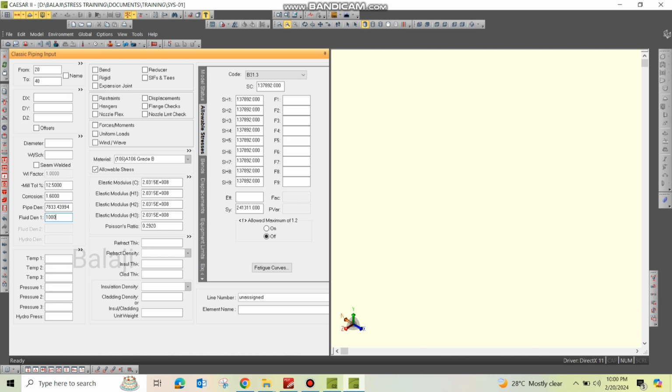In some projects, in the stress design basis as well, clients provide the unit.fil and configuration.cfg file. If they provide them, then you have to create based on those values. If they are not provided, we need to create a unit file, an .fil and .cfg, and send it to the client for their approval. After getting their approval, we will start the modeling.